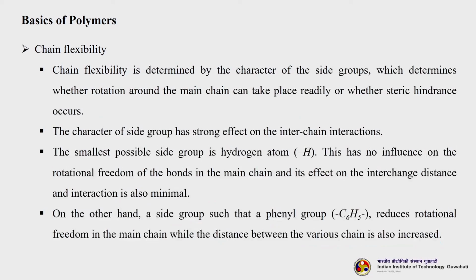So, for this you can impart some of the heterocyclic and aromatic groups to the main chain, so as to increase the flexibility. Chain flexibility is determined by the character of the side groups, which determines whether rotation around the main chain can take place readily or whether steric hindrance occurs. So, the side chain is actually deciding whether rotation is possible or not. The character of the side group has a strong effect on the interchain interactions.